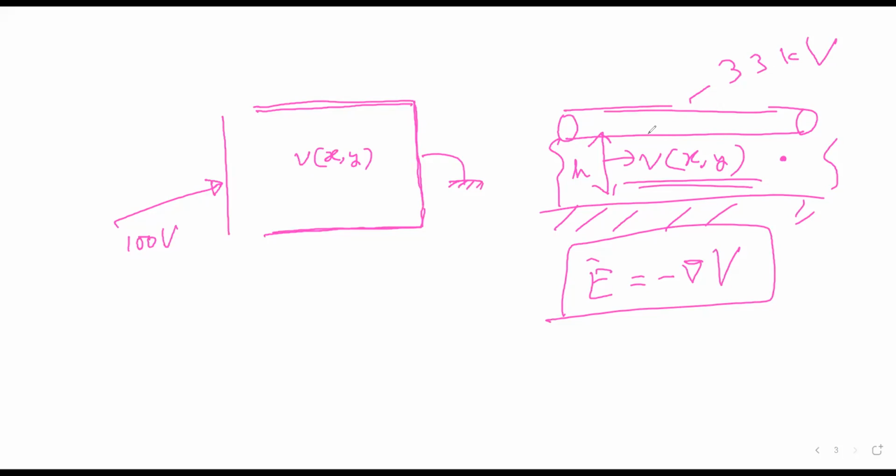Yes, sir. We had a sag calculation. You have a sag calculation, that is good. But you can consider that this point is the minimum point, and if somebody is standing there, then he will be subjected to some electric field. Then how to calculate that electric field, and whether that electric field is safe for him?